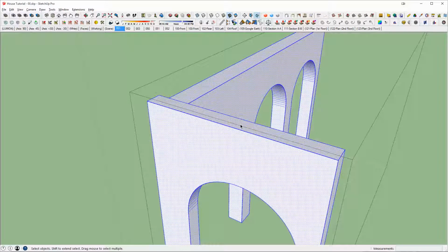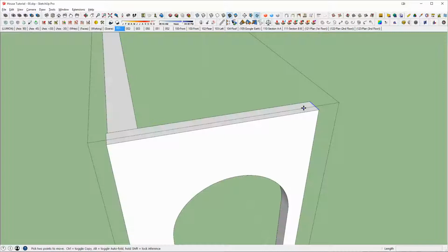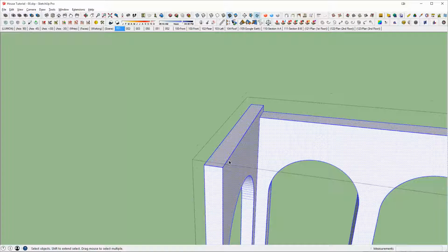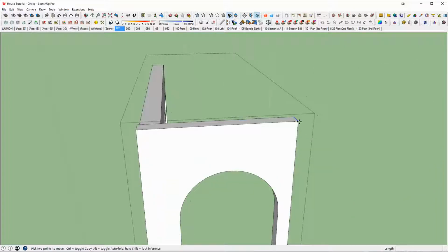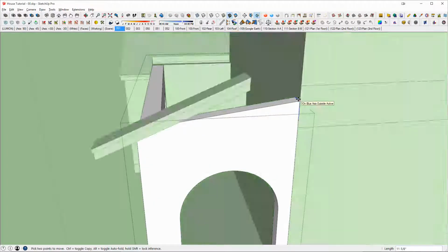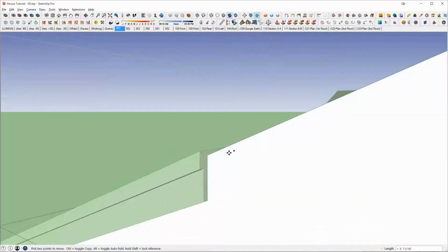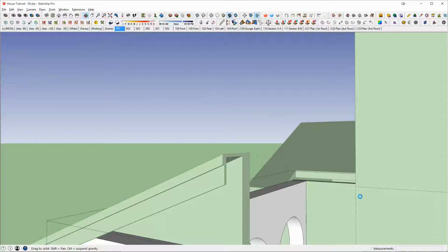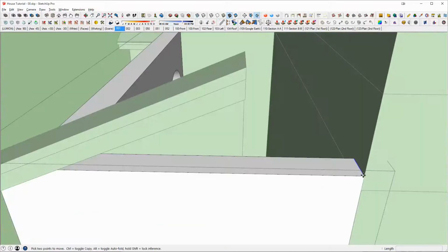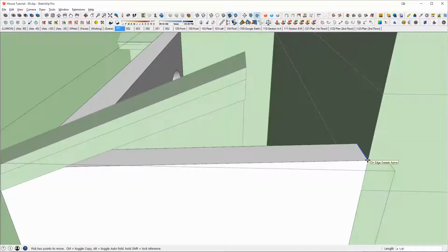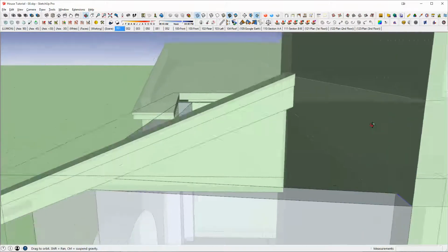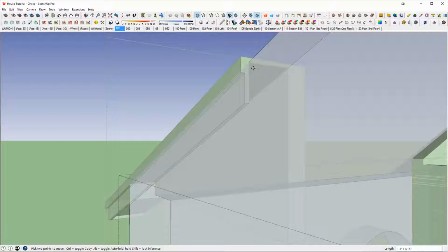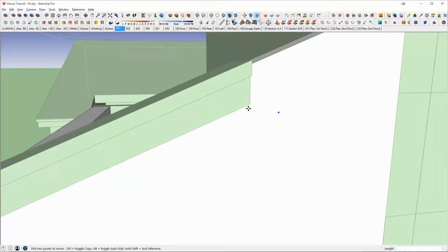Coming back to my wall, I can just simply grab this piece and we'll run our clean command. So now we have a nice clean line to pull. Grab an endpoint, we will run this up and touch this face right here. Sometimes it gets a little funky when it can't see the face, so let me actually go lock it in, holding shift key to the blue axis, and using our x-ray I can now touch this face right there and it works perfect.